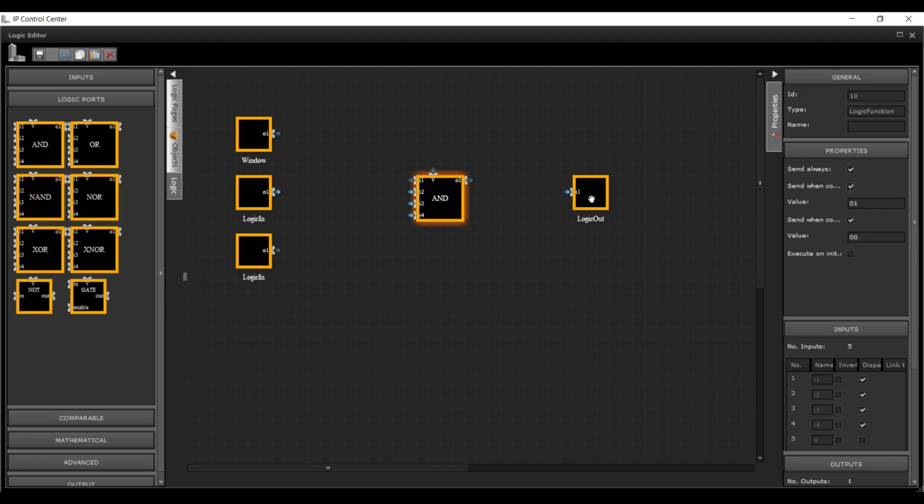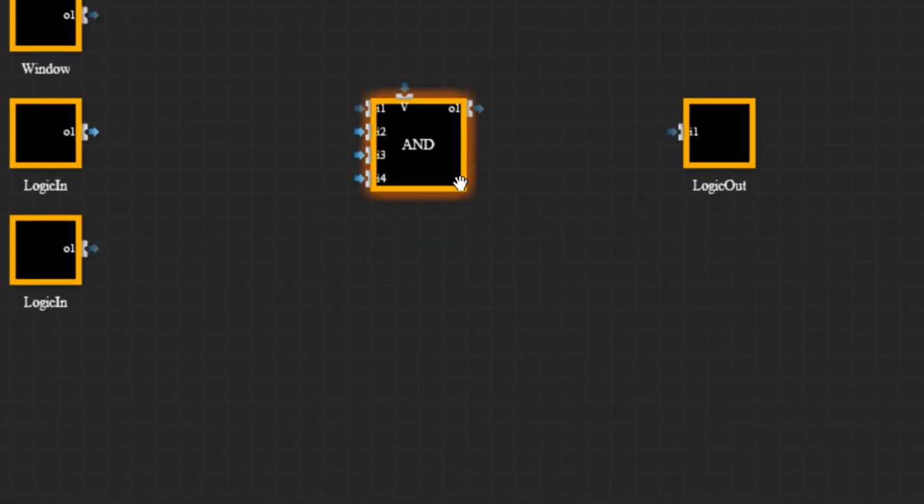The activation input can be linked to various data types. The following applies: if the value equals 0, then the logic is deactivated. If the value is not 0 or not linked, the logic is executed. The logic gates work internally with a double accuracy, as well as with positive and negative values.